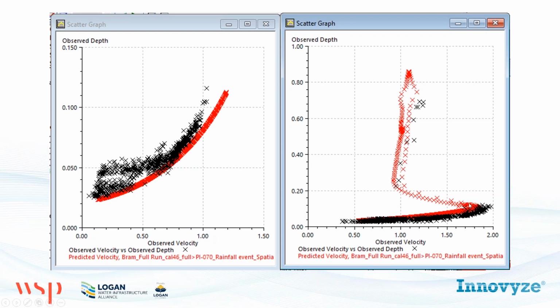So you see that backwater performance up until we hit about 200 millimeters, and at that point, so this is actually a 200 millimeter pipe, we hit surcharge conditions. Basically, as depth increases, there are no further increases in velocity and therefore capacity. In this case, we had surcharge conditions right up to 800 millimeters, but no overflow, just surcharge.